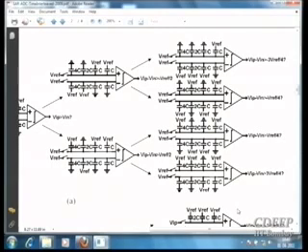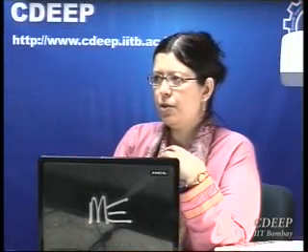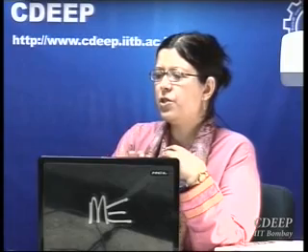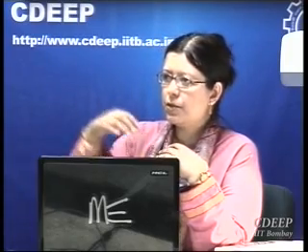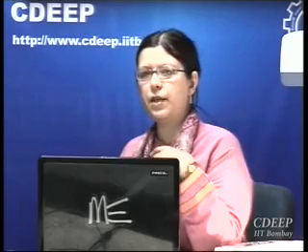In Spectre, what you can do is have an analog module using SPICE language, and then have a VHDL module and use the VHDL module inside Spectre. Now it will do a mixed mode simulation, so some part will be handled by Spectre and the remaining part by VHDL. You don't need to implement it. You can just use VHDL for the logic part.